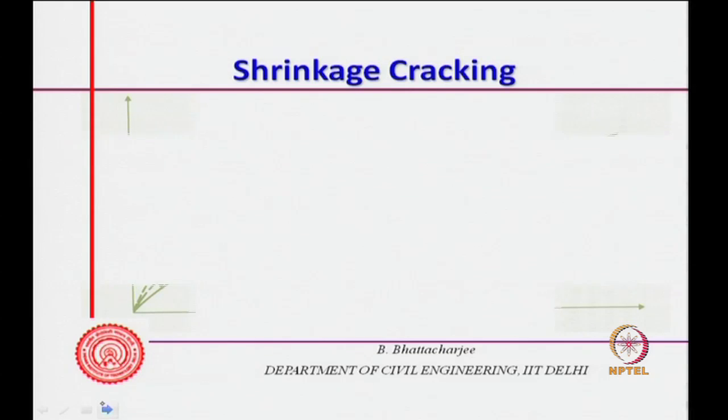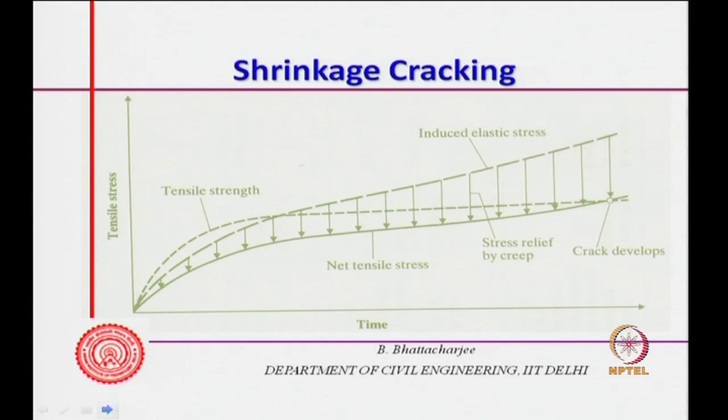But most important, of course, is the cracking, shrinkage cracking. If it is restrained, then tensile stress may be increasing like this. This might be the induced tensile stress because of the restraint, and this will change with time, because shrinkage will increase with time, therefore stress will increase with time, right. And this is the tensile strength.